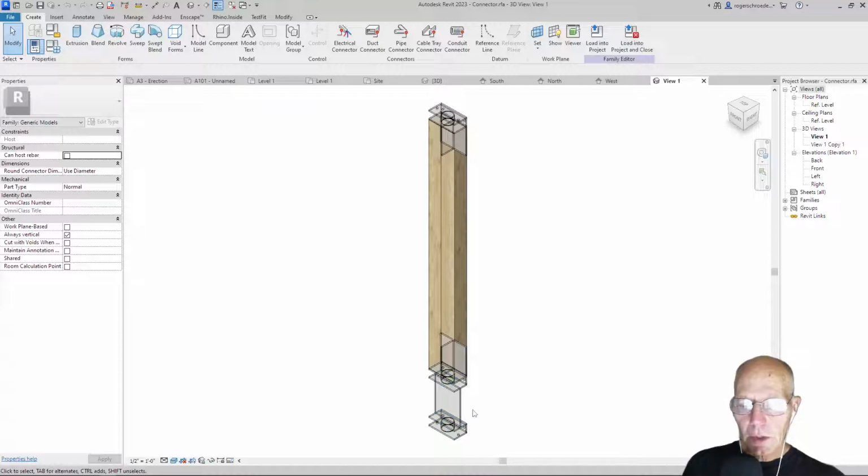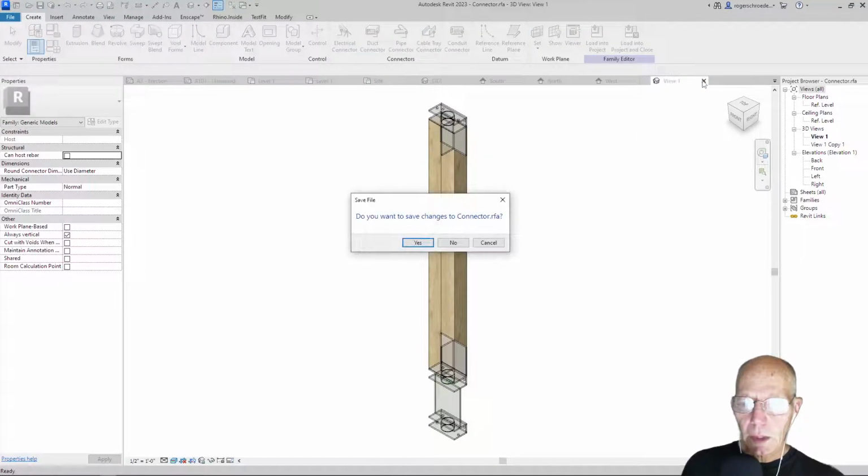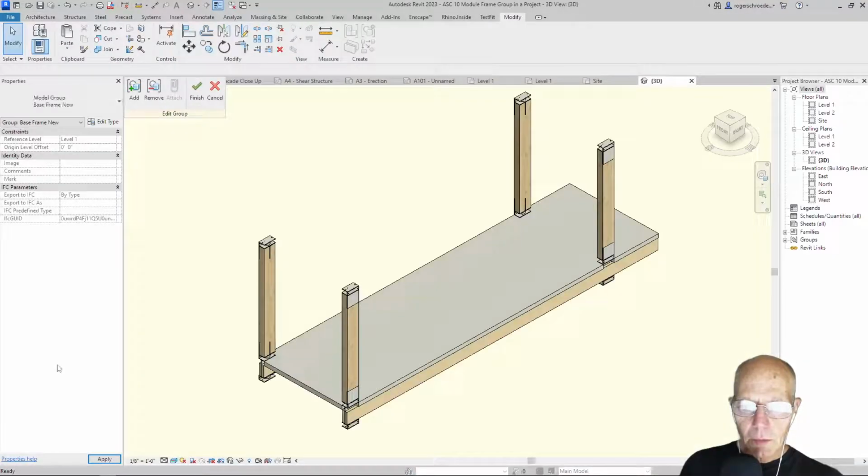The idea here is that mass timber then slides between these elements, the beam, so to speak. So that gap that's created, the load is transferred via this round cylindrical piece of steel. And the gap is there to allow a person to reach in and pass a bolt through and bolt those two assemblies together. So that's probably enough about this assembly. Like I said, I've eliminated that from your construction on this go-round, and I hope that will give you time to focus on other things. So we're back to this assembly.